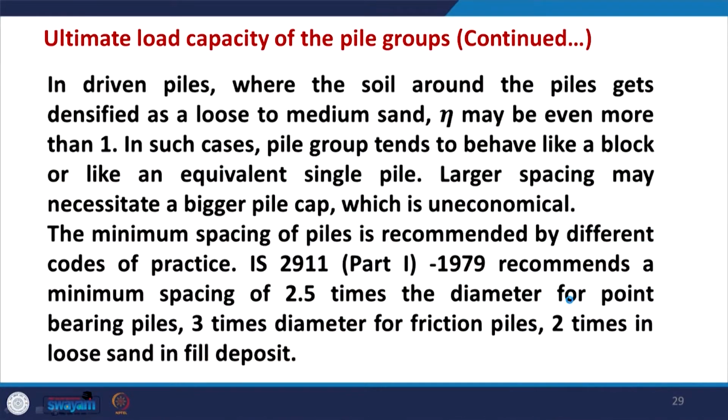In such cases the pile group tends to behave like a block or like an equivalent single pile. Larger spacing may necessitate a bigger pile cap, which is uneconomical. So, this is a thing which we already discussed.